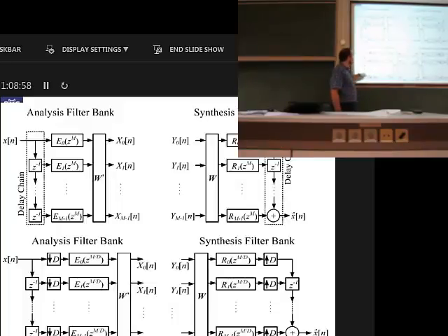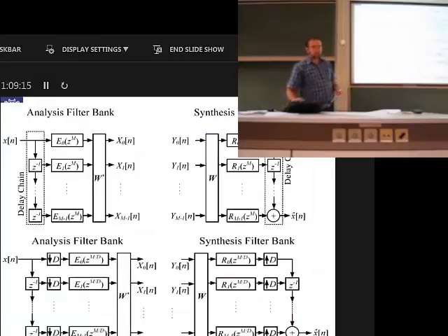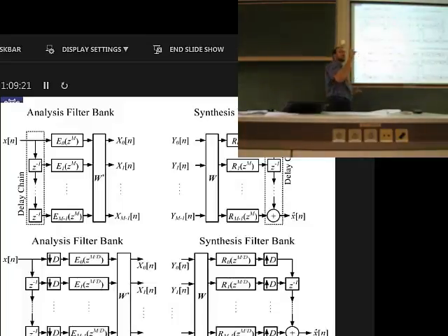So we do for all the paths the same way, and also here for this synthesis part. If you do this, then here you have the filters which are in much fewer taps than what you had already. So you see that here you have E0 up to En minus 1 z to the power of n. So it means that you have a lot more taps than here, which you have m over d.